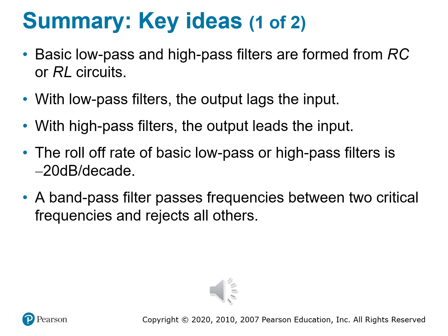So there's a subtle phase relationship that becomes a signature fingerprint to signal processing to let you know whether you're high pass or low pass. The roll off reality: we talked about roll off rate, so let's talk about the reality of that. The roll off rate of these simple filters is a steady negative 20 dB per decade. Think of it as the slope of your filter's curtain dropping off those unwanted signals.